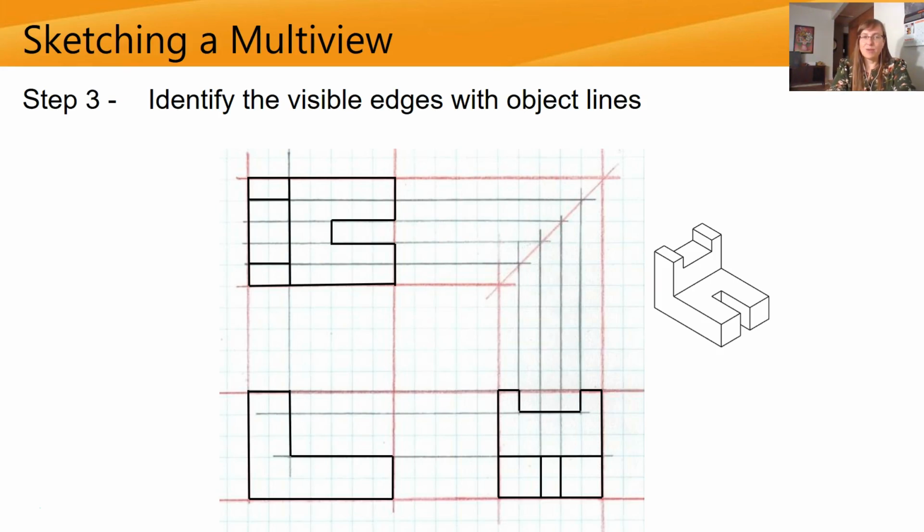And then the top view, if we've drawn enough of our lines, you can see every line that we draw on our top view can actually connect to something in our right side view. So that's a good check to make sure that everything connects, each feature connects to the same feature. So like this part right here is this little protrusion. You can see it exists here. If you follow these lines, oh, this is the protrusion right here. So by following the lines, they point to the same feature in both the top and the right side view.